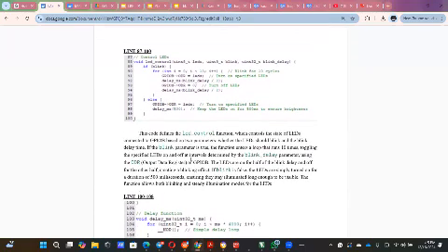So next, line 87 to 100, this part defines the LED control function, which controls the state of LEDs connected to GPIO-B based on two parameters: whether the LEDs should blink and the blink delay time.